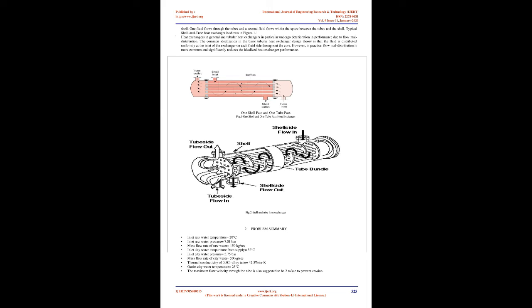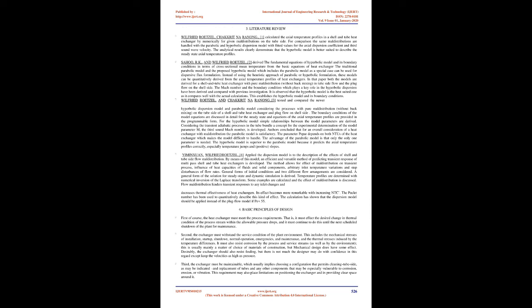The optimum thermal design of a shell and tube heat exchanger involves the consideration of many interacting design parameters which can be summarized as follows. 1.1 Process. Specification of tube parameters: size, layout, pitch, and material. Setting upper and lower design limits on tube length.